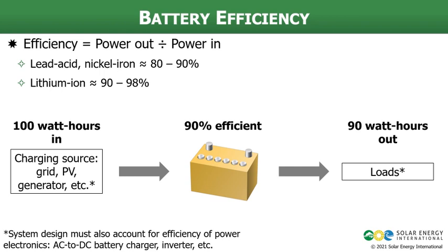In the notes for this slide, there's an example using power. And power is really interesting because in the example in the notes, we use 10 amps going into the battery at 14 volts. Remember, amps times volts equals watts, so 10 times 14 is 140 watts. If we're discharging that battery, the same 10 amps coming out of the battery is going to discharge at a lower voltage, around 12 volts. So 10 times 12 is 120 watts. There we can see that there's an 85% efficiency there using power.